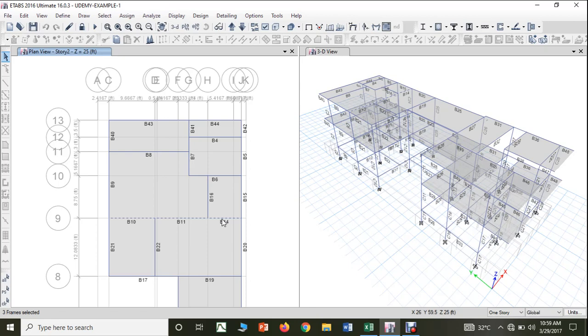Very huge wastage of reinforcements in these beams, because even though the diameters may be different as well as the numbers will be different, calculating the total quantity of steel required as well as executing that in the site is very difficult. That's why while doing the grouping we have to keep in such a way that if we are providing some reinforcement, we try to provide that reinforcement throughout the length.